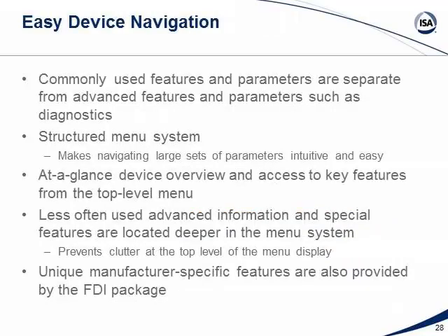I mentioned a little before about context-specific use in developing the FDI specification, enhancing some of the EDDL components. We recognize that there needs to be some sort of common entry points, so that in the end there's consistency amongst the particular packages. And so each one of these device packages has a common entry point for doing device setup. So whether you're dealing with vendor A's device or vendor B, or whether it's a pressure or temperature device, there's a known device setup page where you can go and do all your basic configuration of that instrument.